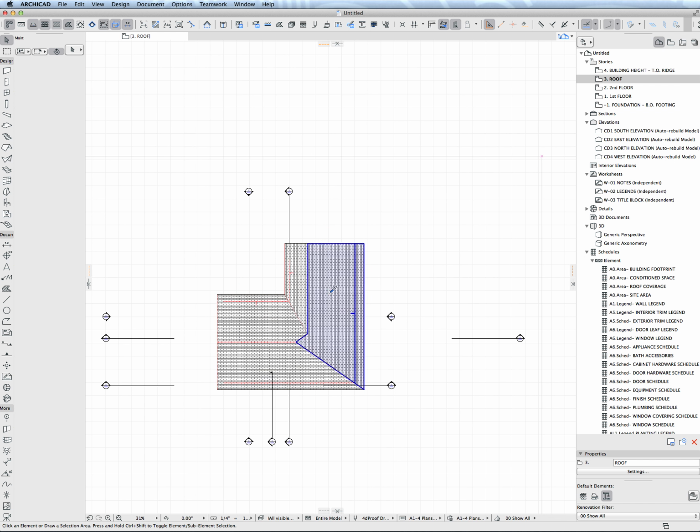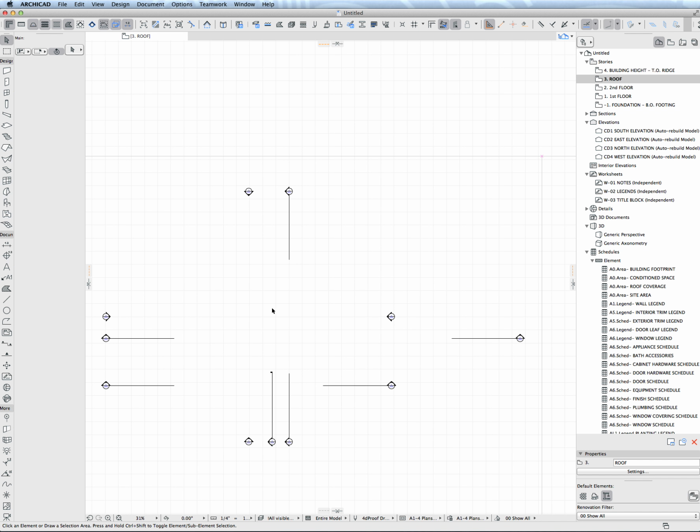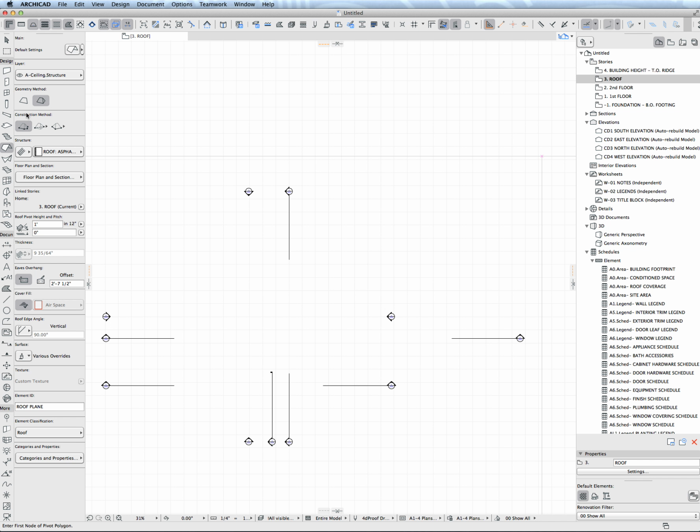And if you wanted to start with a single plane roof, which is what I do most of the time, it's just so much easier, you simply start here and draw a reference line. That's the line that the roof hinges on. Usually I place that to the inside face of the stud and give it a direction. So that's where it's hinging. This is pointing to the ridge, and just draw it out like you normally would.